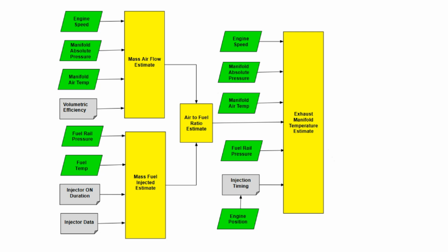This may seem conflicting, but the final calculated exhaust temperature due to the MAP increase will be changed by whichever of the calculated temperature changes is greater. For example, if we have an increase in MAP that causes the calculated exhaust temperature to increase by 20 degrees due to the direct input to the math model, but also causes the calculated exhaust temperature to decrease by 5 degrees due to the air-fuel ratio increase, the overall exhaust temperature estimate will be increased by 15 degrees, for an example.